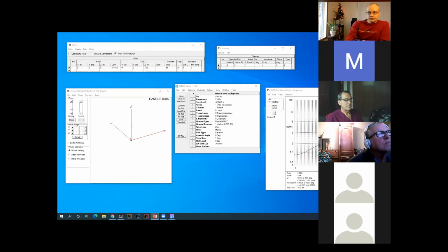Question, Fred. Yeah. Inverted V. I didn't do the rotate. I just lowered the ends on the Z axis. Does that have similar performance? Yes. Well, when you just lower the Z height, if you think about it, remember Mr. Pythagoras, you're actually changing the wire length too. I didn't think it changed. Yeah, it will.